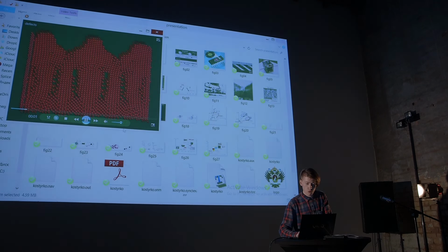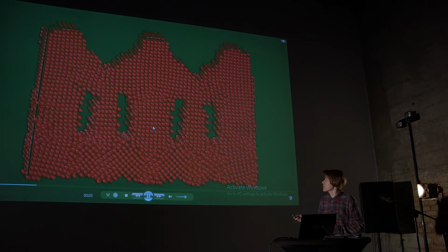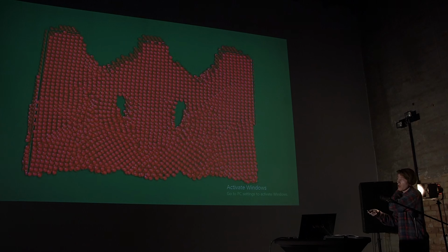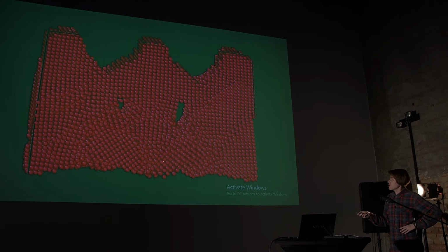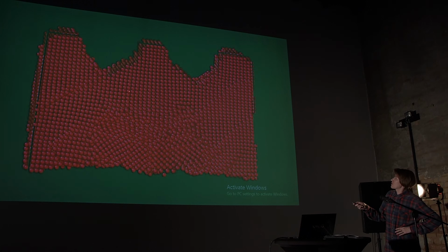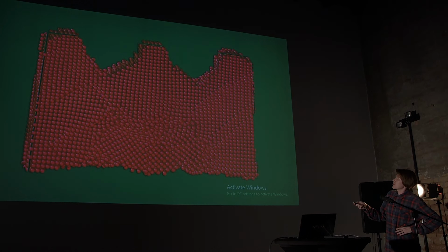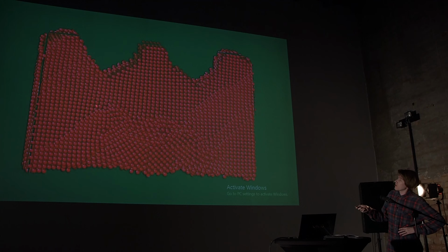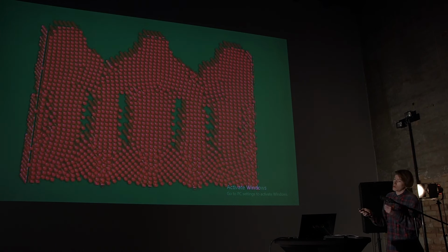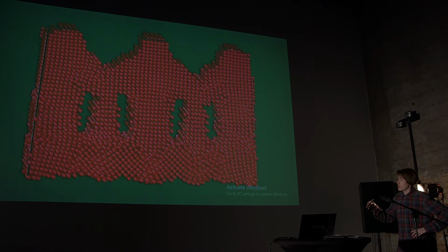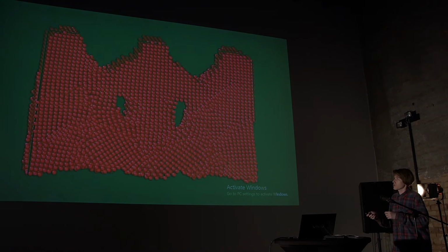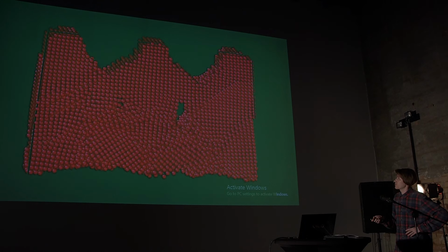And also on this video we can see nucleation of microcracks here on the free surface, and also you can see, I hope you can see, because it's not so clear, but here we have some distortion of our crystal structure, its dislocations, and then they can also produce different stress effects.